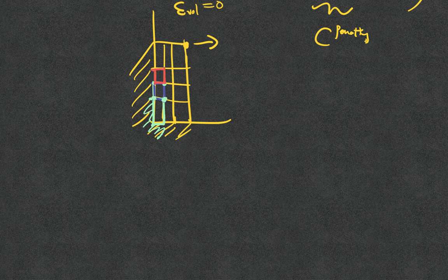So this point is fixed. These two points are fixed. Can I move this point? I also cannot move this point, etc., etc. Eventually, the whole thing cannot move. Okay, not now. Theoretically, it could move, because the shear modulus is finite. The bulk modulus is infinite, right? You get the point.